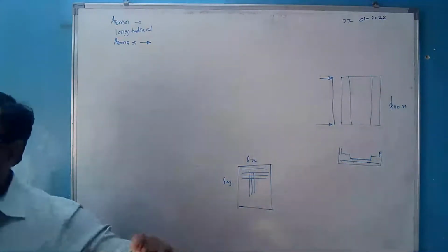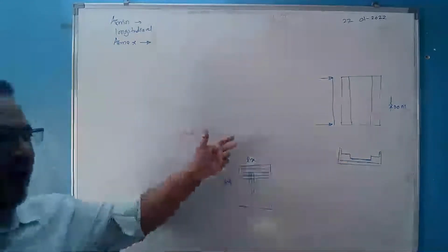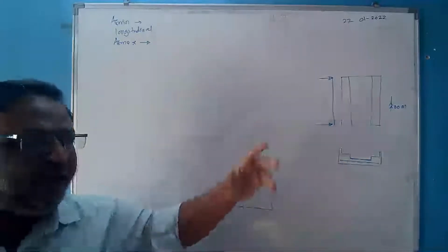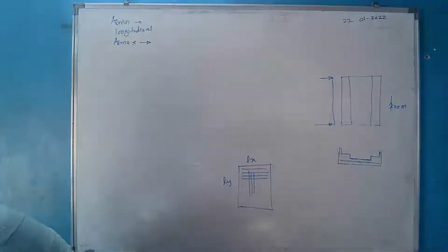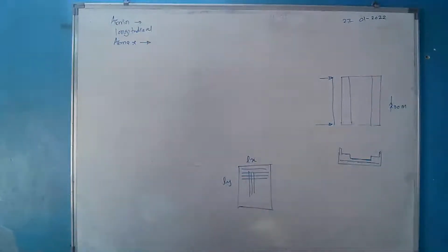मिनिमम के लिए हमने दो तीन criteria देखा था अलग अलग. One from the ductility requirement, फिर वहां पर एक था 0.0013 bD, उससे कम नहीं रहना चाहिए. फिर दूसरा एक criteria था crack control से. We had calculated the minimum area of steel required from the crack control criteria also, and the greater of the two is to be considered as the minimum area. कुछ 1100-1200 कुछ आया था, I don't remember now. कितना था Aamir? Are you there? हाँ, thank you Aamir. 1127.8.